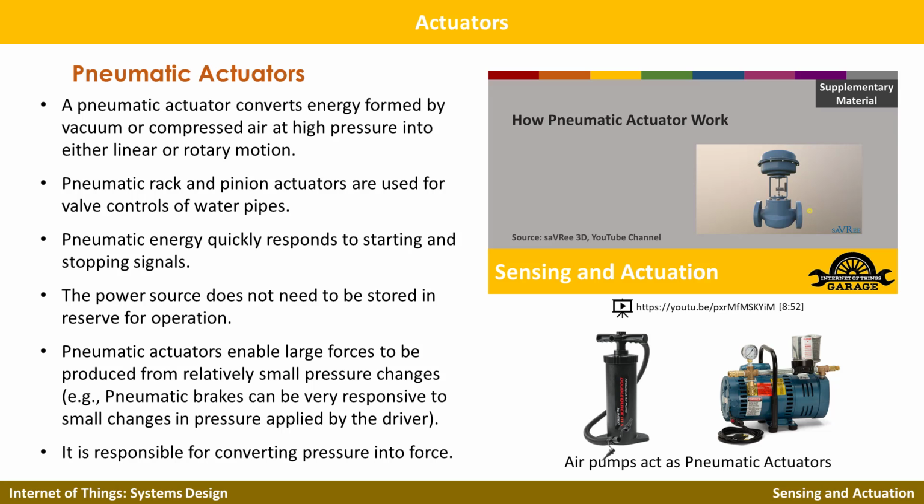Pneumatic actuators are somewhat similar to hydraulic actuators. Instead of using liquid, pneumatic actuators use air, so the compressed air, or it could be vacuum, to generate the pressure, which will convert into linear or rotary motion. Pneumatic actuators are typically used in control valves, water pipes. So if your IoT system is using some kind of valves, there's a likelihood you will end up using this kind of actuator, or controlling water systems,